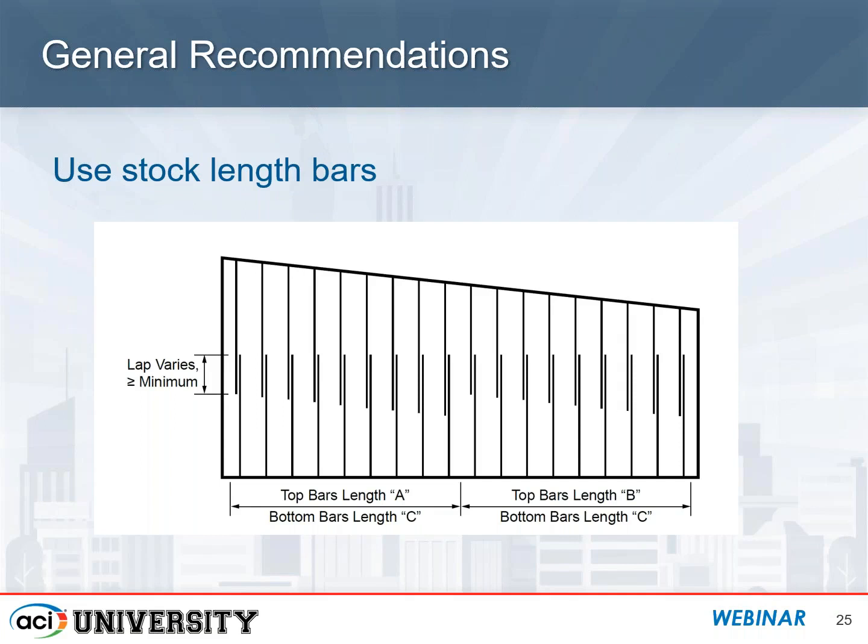Using stock length bars, and also lengths of bars that you can repeat very often. And I always like to show this particular example. What you're looking at here is an elevation of a wall that changes elevation over its length. Now, your first impression might be to provide just single bars along the entire length and then vary the length of those bars. Well, that's difficult in a number of different ways, especially placing the bars in the field, because each bar has to be labeled with respect to what position it has to be along the length of that wall.